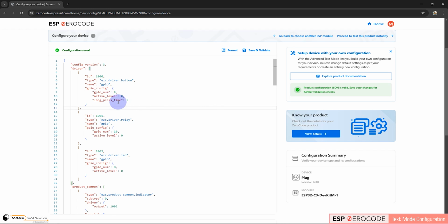So sometimes you need to change this active level to active high. For example, in our case, the indicator LED will get turned on only if we provide logic high to it. So what do you think, how should we update its active level? Yes, you are right. We have to make it active level high. So here you can verify it, the light active level. When is the output turned on? If we put 0, the output of the pin will be 0 volt. If we put 1, the output of the pin will be VCC. Hence, it will glow the LED.